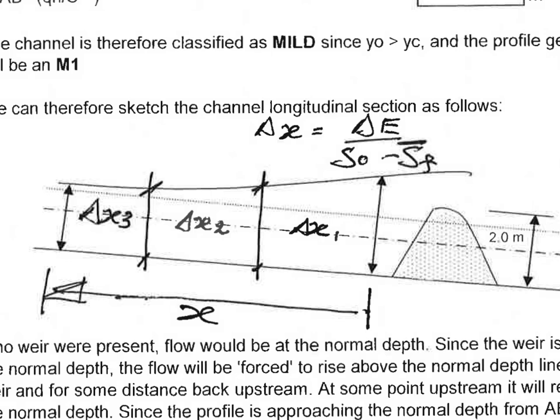Now, in our table, as we'll see in a minute, what we would do, draw up a table. We have the starting and the finishing depths. We have our intermediate steps, which we choose, and we calculate for each of these sections the specific energy, E, y plus v squared over 2g. And we also calculate the slope of the total energy line at each section from Manning's equation, that's SF. And the bed slope is S0, so that's the slope of the bed here. What is SF?